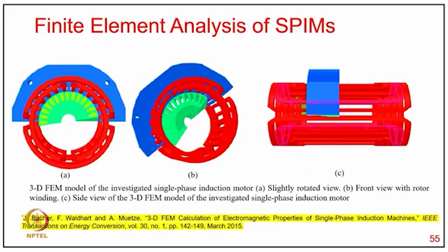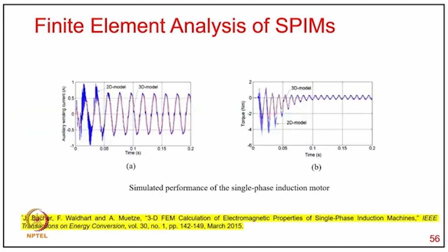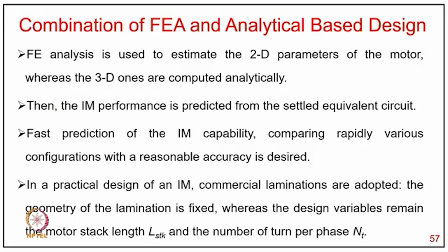for performance, which is electromagnetic and thermal performance, and then of course structural as manufacturability. Here are the fundamental elements of a single phase 3D FEM model of the investigated single phase motor: a slightly rotated view, the front view of the winding, and the side view of the 3D FE single phase motor, which is reported in this publication as a design of a single phase motor. And these are the typical simulated performances of the single phase motor designed using finite element analysis.